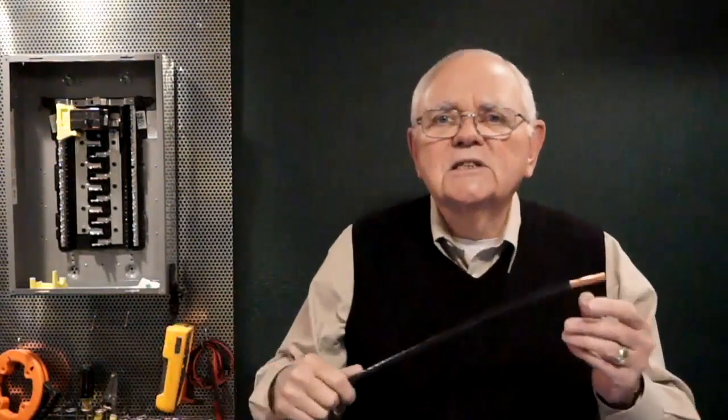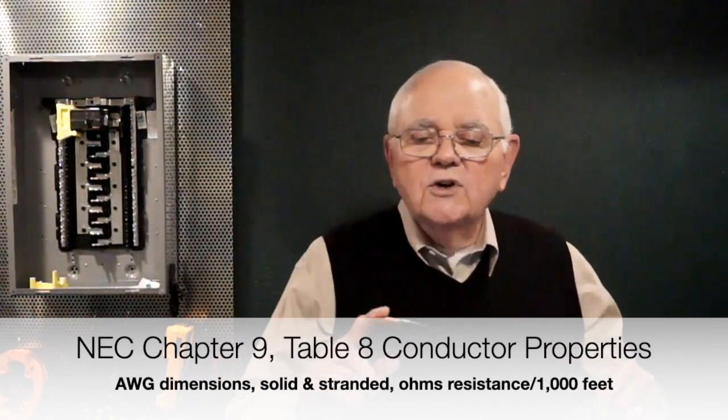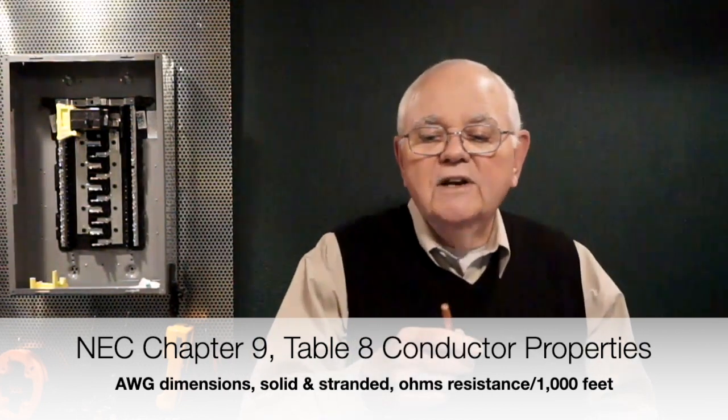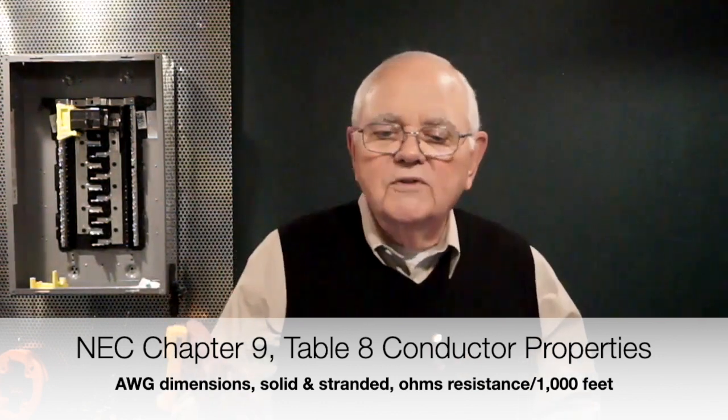There are pluses and minuses for each type of conductor. If you go back to Chapter 9, Table 8 in the code, it gives you the physical properties of our various types of conductors, including their dimensions. For instance, all conductors 8 gauge and larger are required to be stranded per the code.